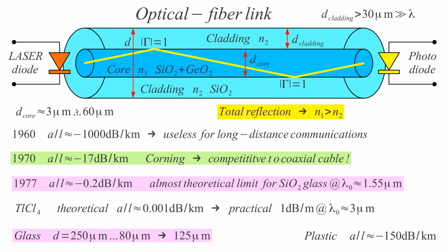The good fibers, the single mode fibers, actually require a core of 9 micrometers, and 9 micrometers is very difficult to splice. That's the main reason for the cost. Not just to splice, but also to couple to the laser and to the photodiode. And this is the reason for the high price of optical communication. Otherwise, optical fiber is extremely cheap to manufacture. It's by far the cheapest type of cable we can make.